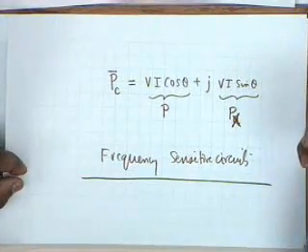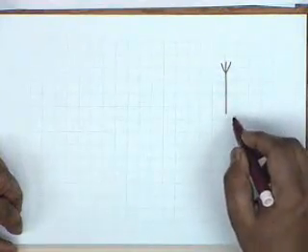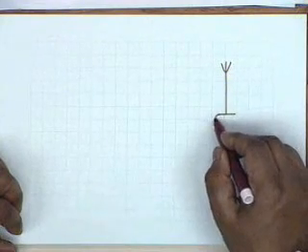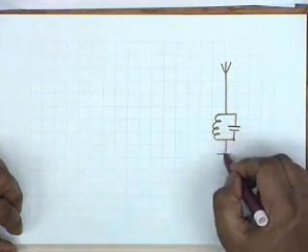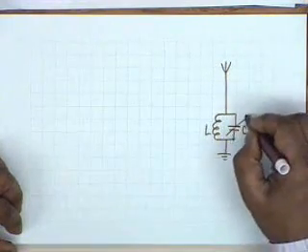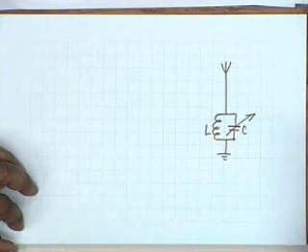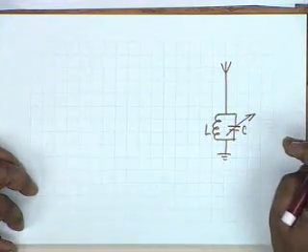Now, different transmitting stations are transmitting at different frequencies, and what you basically do is, this is the aerial, you have an inductance capacitance circuit in parallel, L and C, and tuning, what you are doing essentially is rotating a capacitor knob. So you are varying the capacitance.